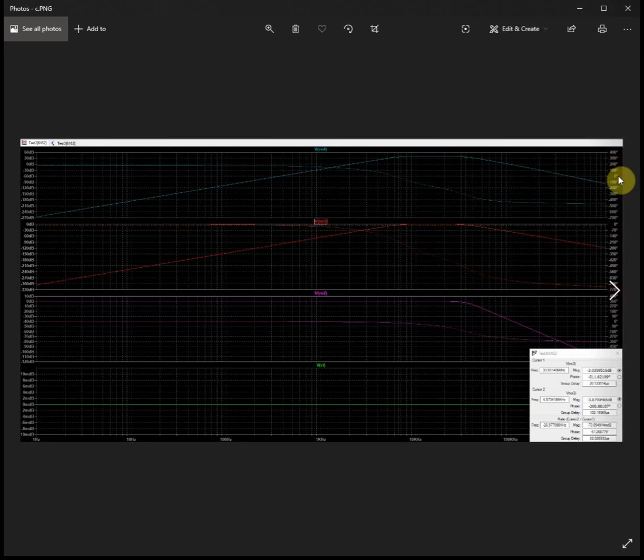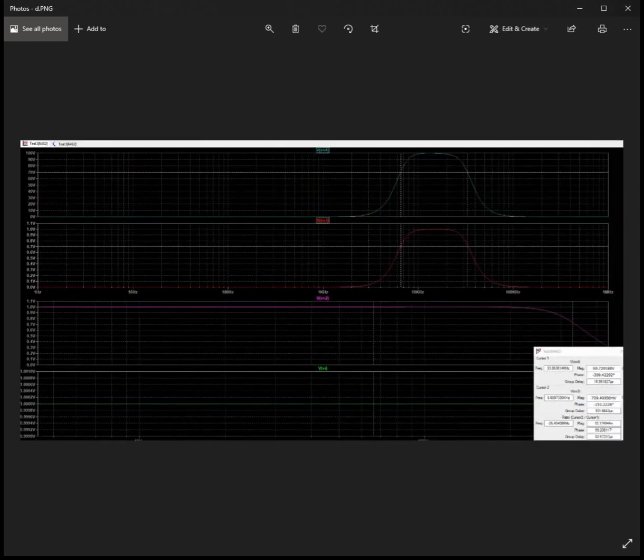And here in our last figure, we can see that the VO4 has 100 times voltage gain compared to the VO3. Other than that, there are almost no differences, as we can see that the Bode plot shows us that it passes anything between 6600 to 33,600, where the Bode plot cuts off at those frequencies.